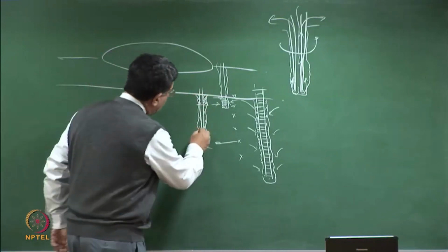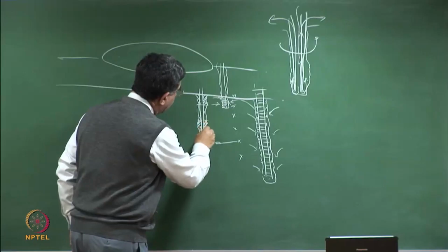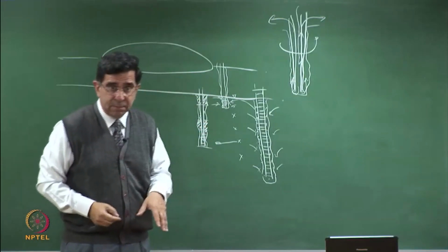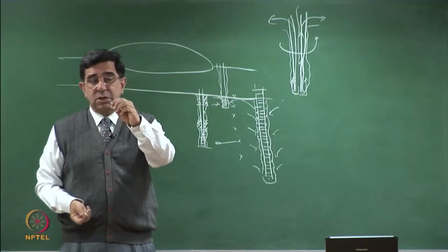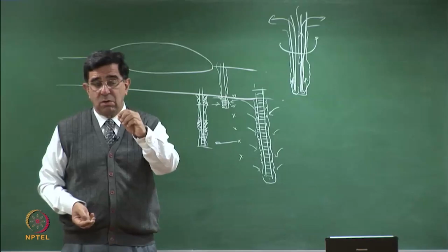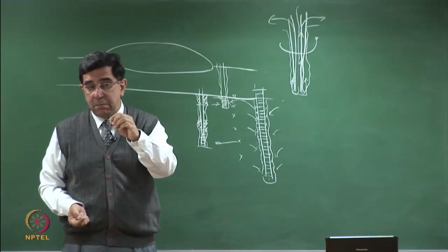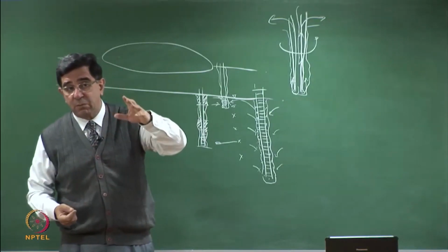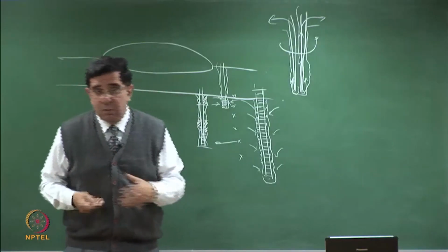So you have to seal off here, so that no water can come from the upper layers and meet the bottom layer. Therefore, establishing the groundwater contaminant concentration requires picking up samples from specific points, and you should not have any interconnectivity with the other points.